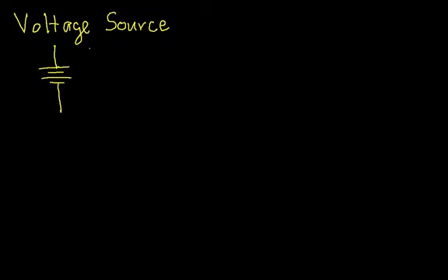This is background information that hopefully you'll be able to refer to when you start working circuit analysis problems. So we'll start off by talking about a voltage source. And we typically have two schematic symbols for voltage sources. The first one you've seen if you've watched previous videos. It looks like this. And then you typically label it with a voltage, say 3 volts. This represents a constant source. And the idea is that the 3 volts here that the source puts out doesn't change.